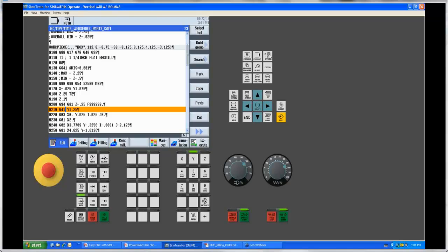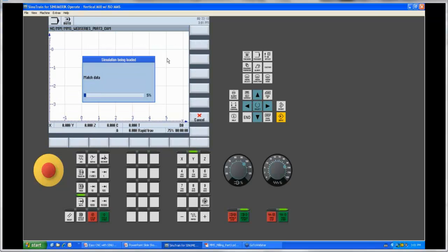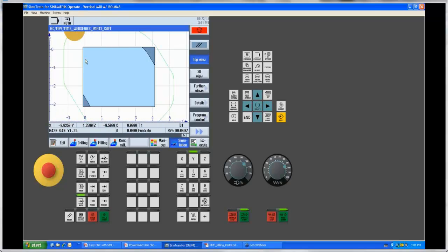So what it will do is it will mess up what the solid looks like because we're looking for that diameter. So although you can certainly do it, when you simulate it, it's going to look like you're either offline if you have the full diameter. See there, I'm way off the part, or if I zero it out, I won't get the tool represented. So that's